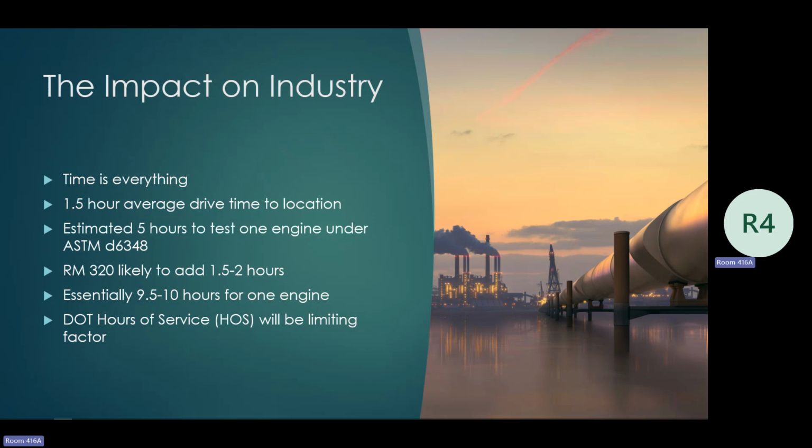So if we say a typical test takes 5 hours right now, if you're doing all of your calibrations, doing your stack work the way that you're supposed to be doing it, if you're getting your method 2 exhaust flow measurements, from the time you hit the location to the time that you're done with engine number 1, you could safely assume about 5 hours of testing. Okay. Every location that we go to on average is about an hour, hour and a half away from us.